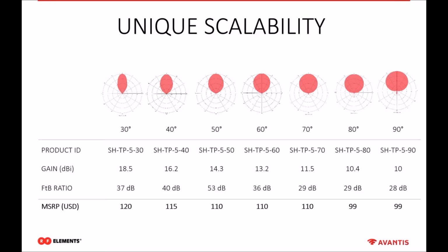And maybe you are wondering that 18.5 dBi gain is not that much, but don't forget symmetrical sector antennas don't have side lobes, so all the energy is radiated to the main lobe. So don't be confused by this gain.